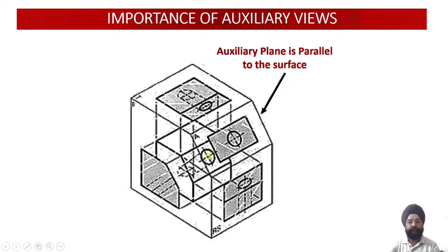But if I look at this object from the front, let us say this is my front view, this circle will start appearing to me like an ellipse which has been reduced from the height side, and this appears as an ellipse which is located horizontally. So if I start manufacturing this component, I am not going to get my desired component appropriately. So this shape is getting distorted. So the ellipse is oriented horizontally.